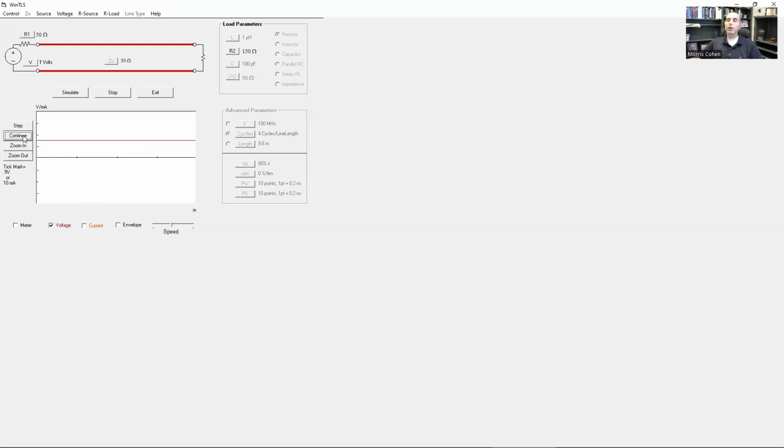We have 3/4 of a volt that now appears across the entire transmission line. We've reached steady state. The load has its 3/4 of a volt, and we have the correct voltage established everywhere. Now, let's think about that for a second, because if I go back to the resistor divider rules, if there were no transmission line here, and I just gave you a battery, a 50 ohm resistor for the generator, and a 50 ohm resistor for the load, and asked you what's the voltage on the load, you would say, of course, resistor divider rules, that's 3/4 of a volt. Hey, that's exactly what we have established, despite needing this back and forth reflection.